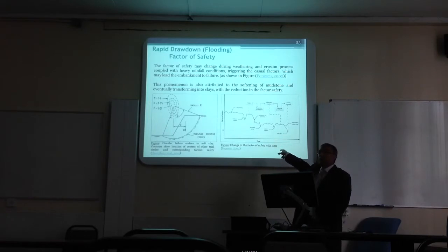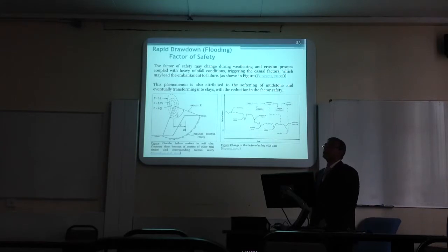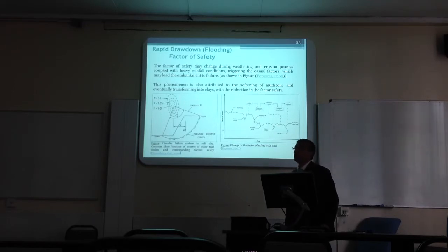Due to heavy rainfall, as I mentioned, the mudstone will convert into clay. As every hard rock which is susceptible to weathering, it will get deteriorated and softened with time, with weathering and water. How do you show that the slope is still stable and there is stability in your design? Considering the time, it will.